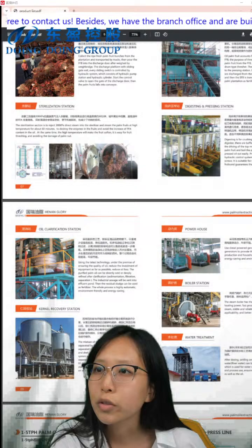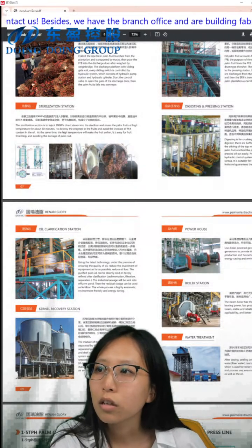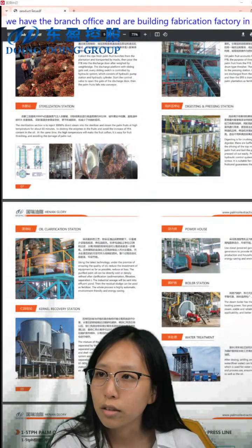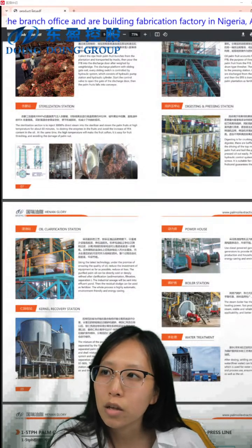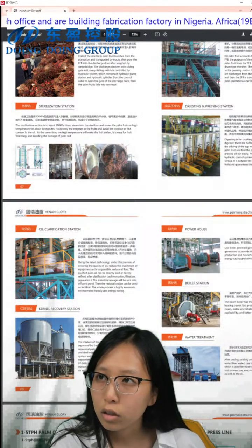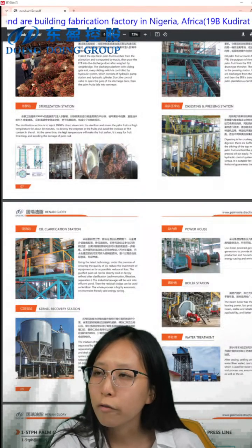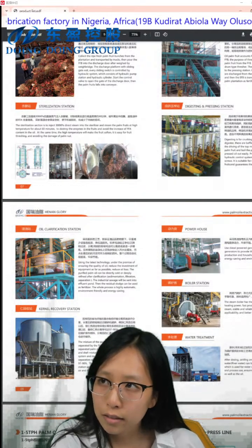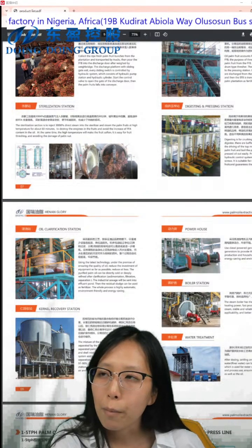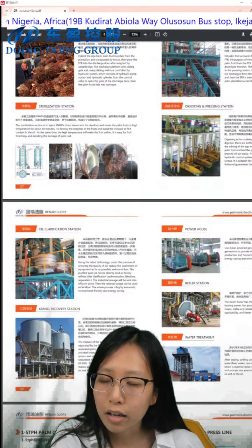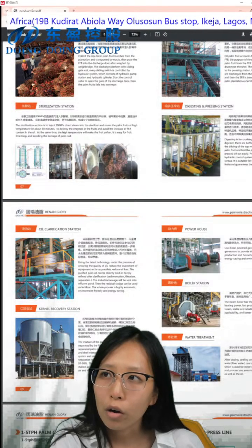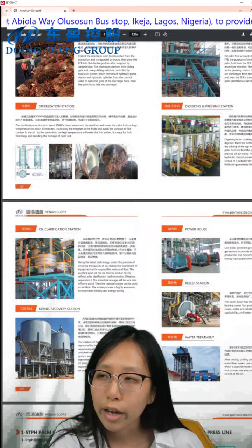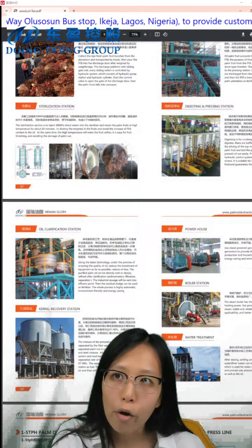This is the sterilization section. We can use the vertical sterilization machine. We use steam to make the fruit soften. After this section, the fruit will be easier to process, and we can get more palm oil. Also, the FFA will be reduced to guarantee the quality of our palm oil.